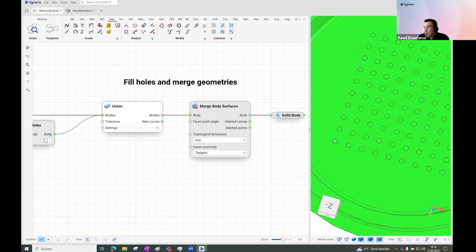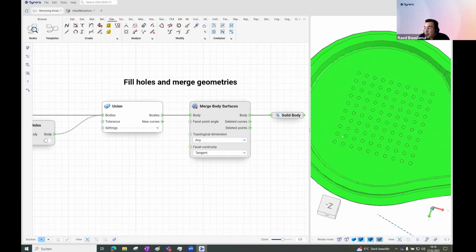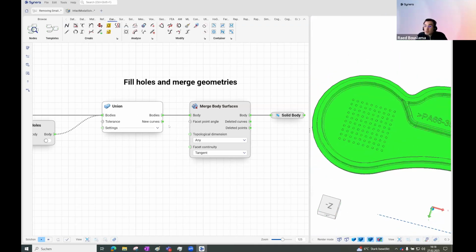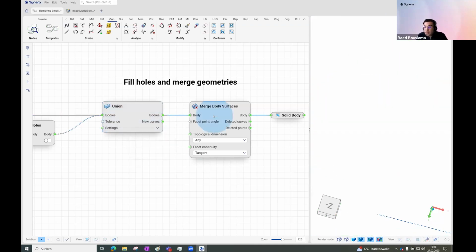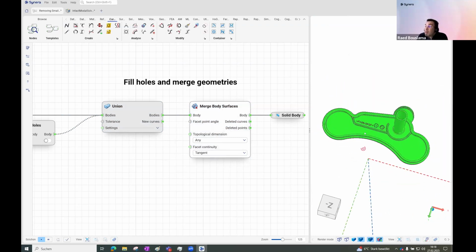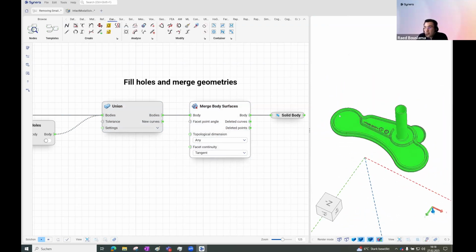Since this is a batch surface already, we don't need coincident holes to be on these curves, for example. Therefore, we could also merge body surfaces. At the end, we are left with a clean body that is also optimal for CAE tasks, for meshing afterwards.